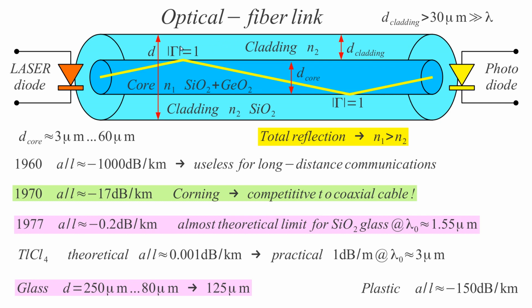Since we have here an exponentially decaying field in the cladding, that field decays before it reaches some lossy component here. The size of the core is another variable we have here, and the core size may span from 3 micrometers to 60 micrometers for conventional near-infrared light communications.